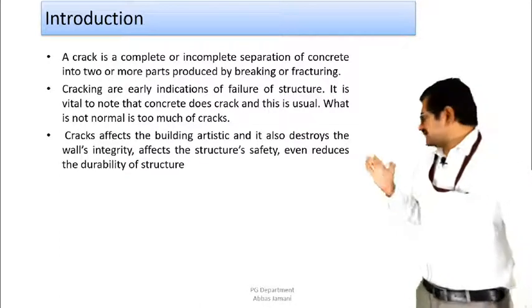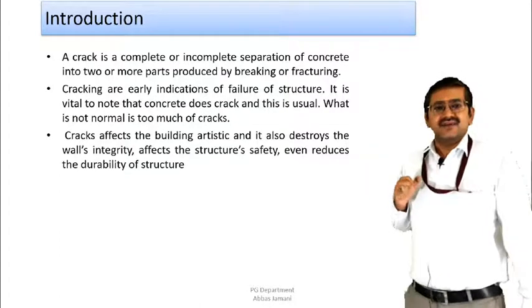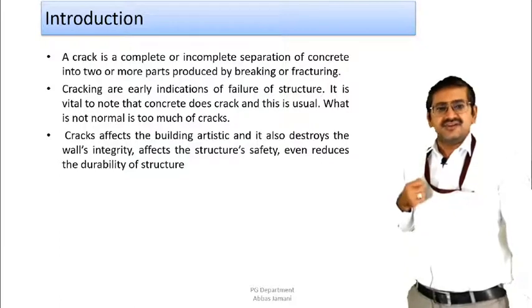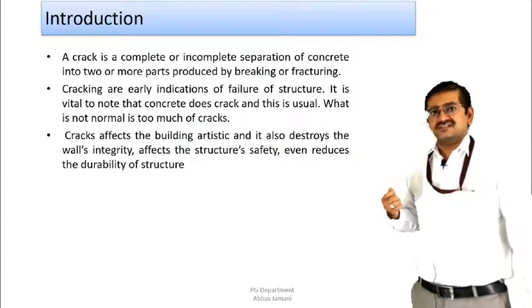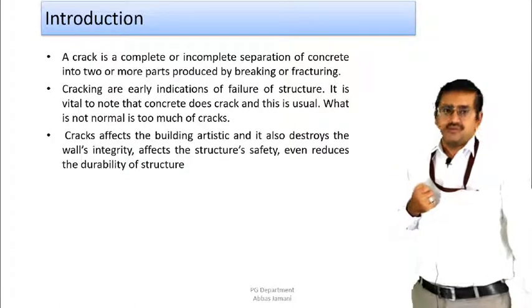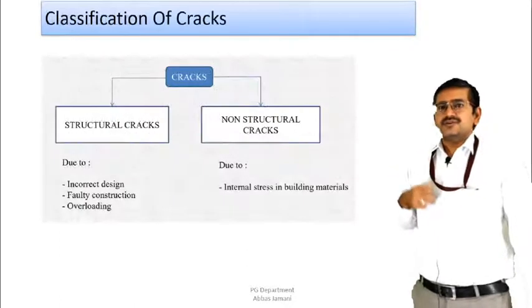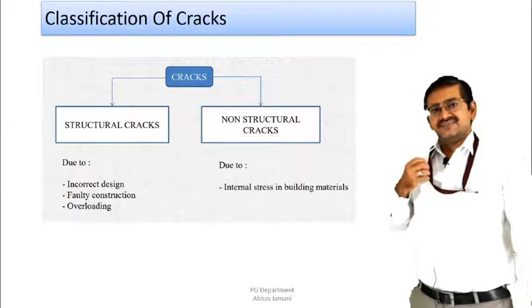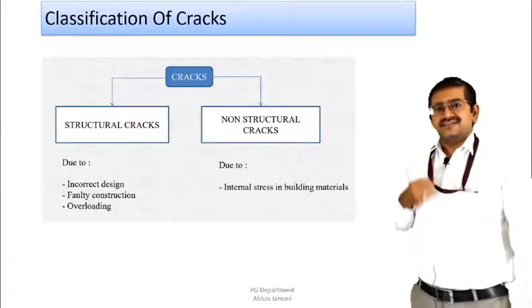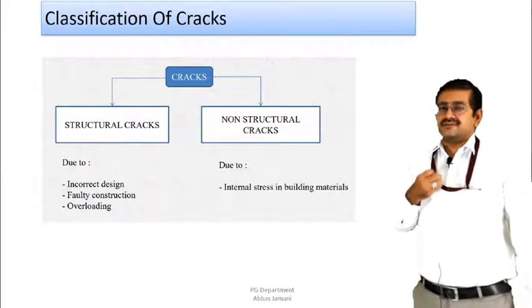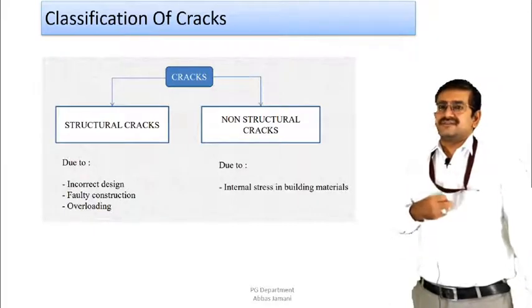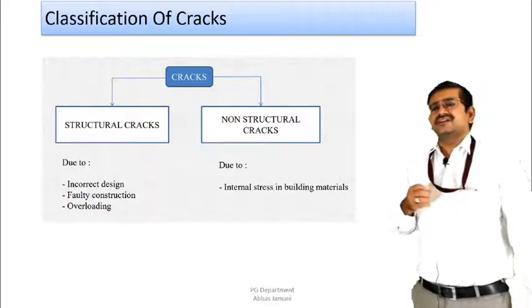So if you talk about that, the cracks are going to affect the building aesthetics, and they also destroy the integrity of the structure. Also, they may affect the service life and the performance of the structure overall, right? So after seeing this basic definition of crack, as I said, just on the visualization of the crack, you cannot decide whether this particular crack is going to be harmful for the service life of the structure. First, you need to understand the type of the crack.